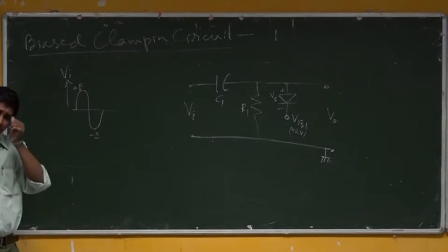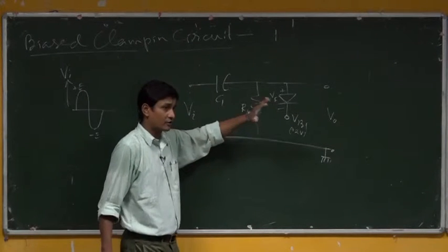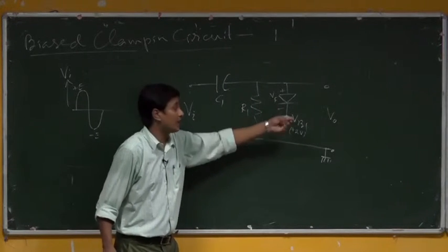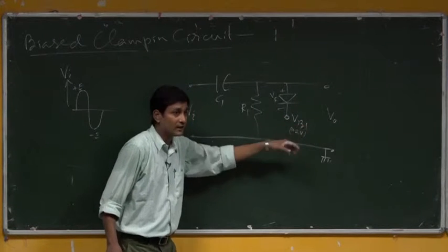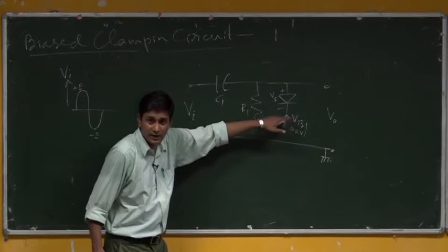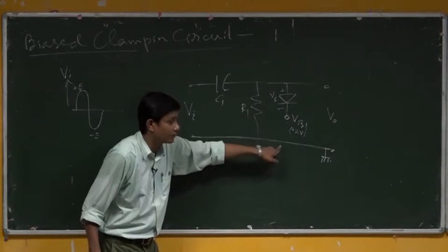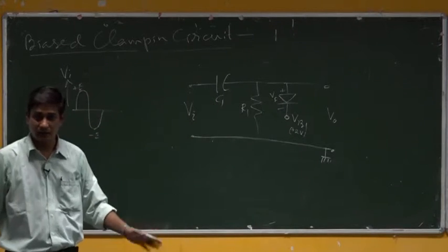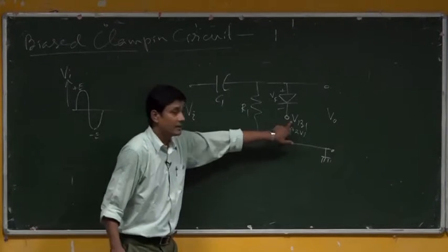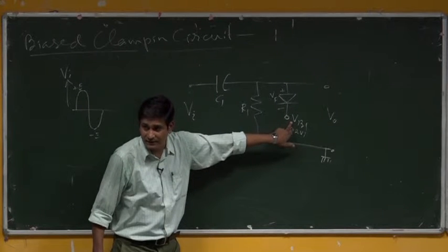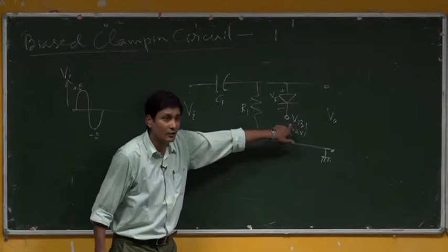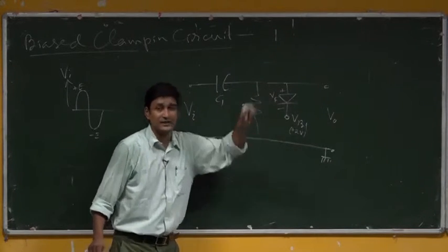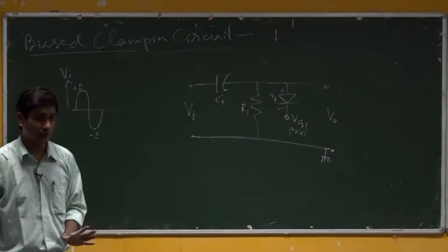We have already analyzed some circuit for clipper in biasing condition, if external bias is applied as VB1 there. So, for that, which way to change the connection here? By putting plus and minus here, then finally going to the ground. Those things I am not making here as a redraw of the circuit. Straightforward, I am considering that if VB1 biasing is applied in this circuit, it has a potential of VB1 with respect to ground, which is positive. In this example, what I have considered is, say, 2 volt, plus 2 volt.